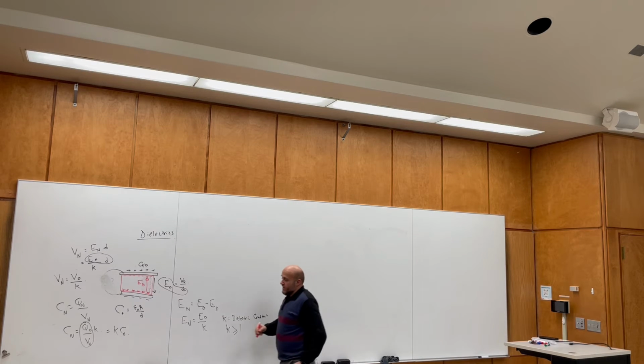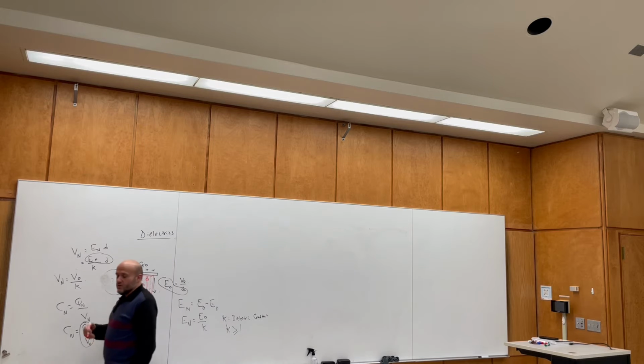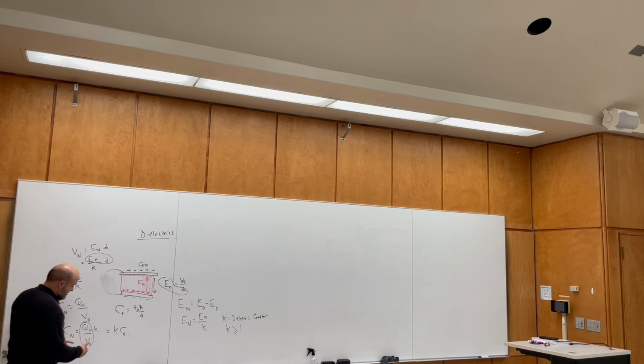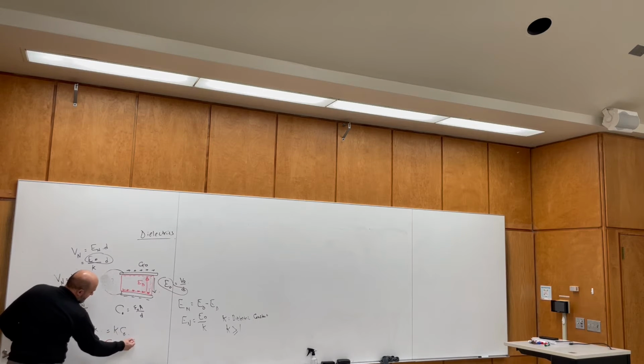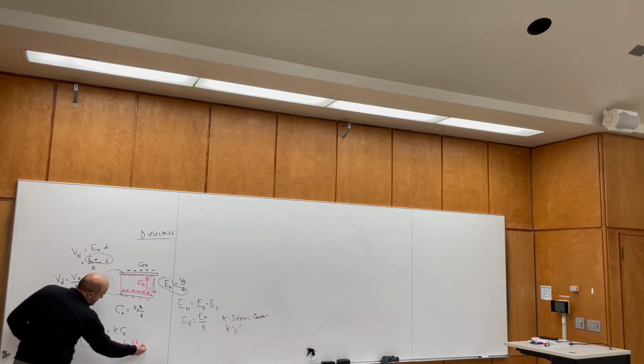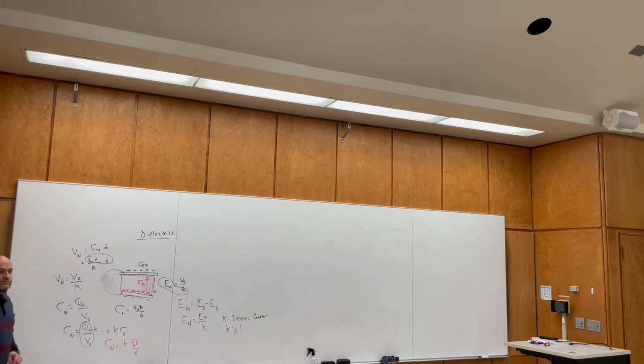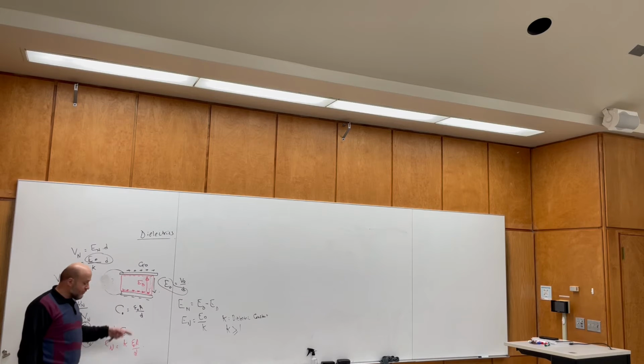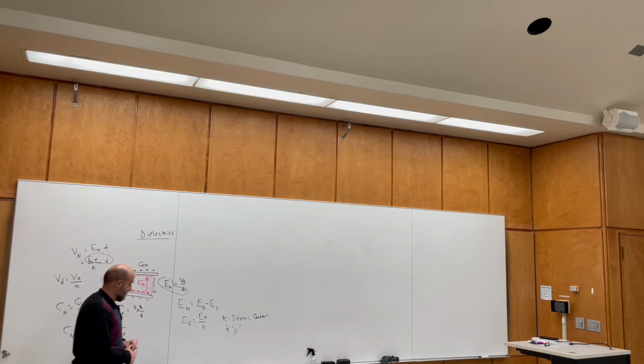So the dielectric material, they increase the capacitance using this. I'm going now to do one example. So basically the new capacitance, I can write this as K epsilon 0 area over D. Of course, if it's air, as we used to do before, K is just 1. If we have another material, we multiply by this constant K.